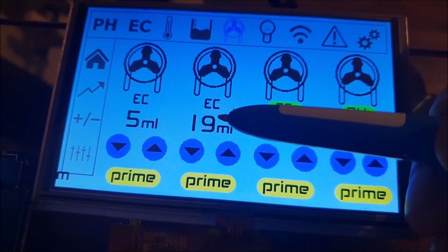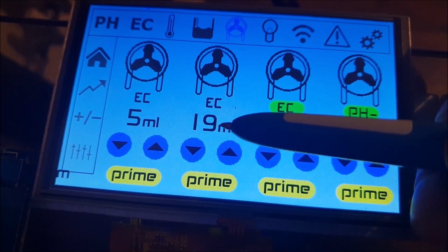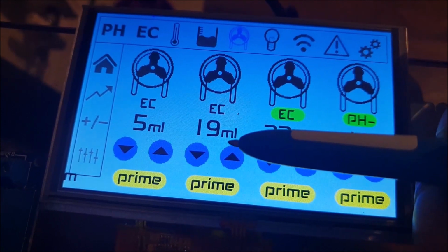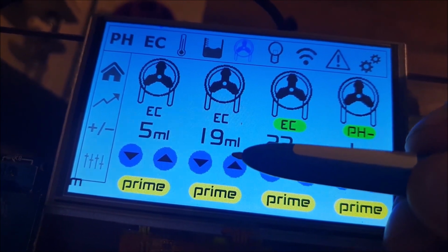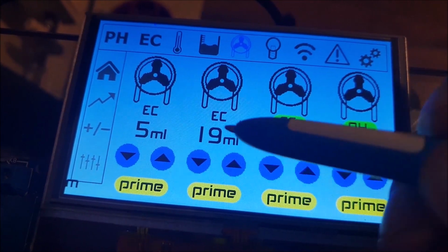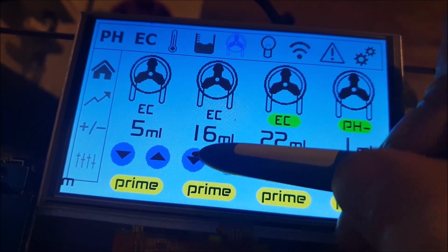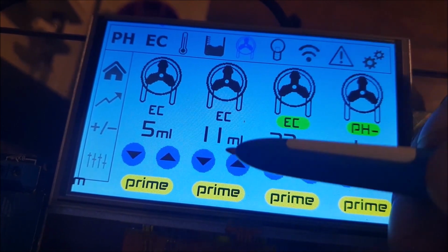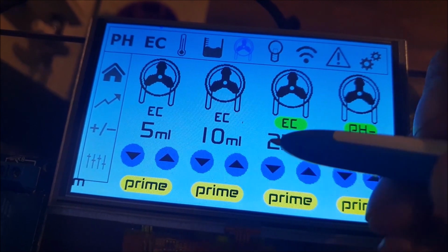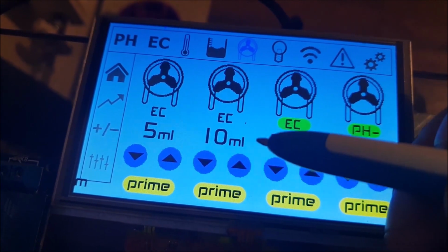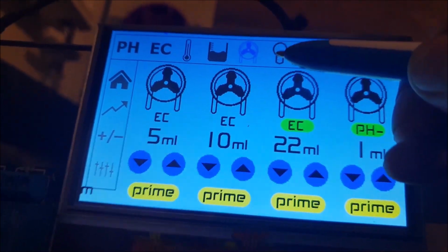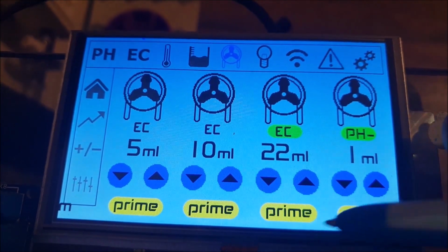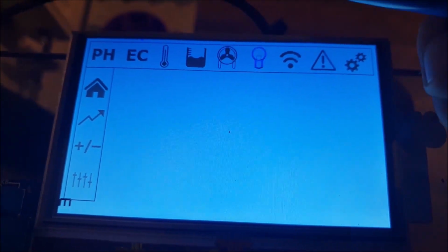And if you're thinking, well, that's still pretty slow, I've put in a 200 millisecond delay between increments, because if you had the default, it'd have got to 1,000 far too fast for you even to count. It's very, very fast at refreshing. I just find that with any less than a 200 millisecond delay, you press the button once and it's gone up 5 or 10. And even then, as you've seen, it can do a little ghost press, but that's just to do with the interrupter software emulation. Right, so that's doses. Change the modes, set the values, prime them, and we've got our light control tab.